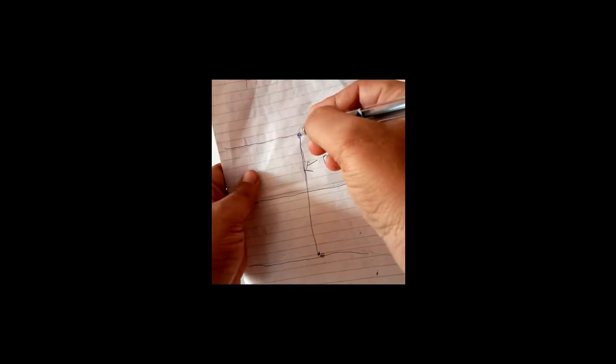So this is your front view, and this is your top view. If that point is capital A, then this point is called A dash and this point is called A. This I have already explained in the previous video. That is, the front view is denoted as A dash, B dash, C dash like that, and the top view without dash, A, all in small letters. So this you should understand. That is a projection line.